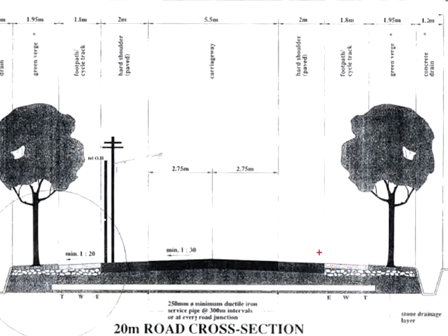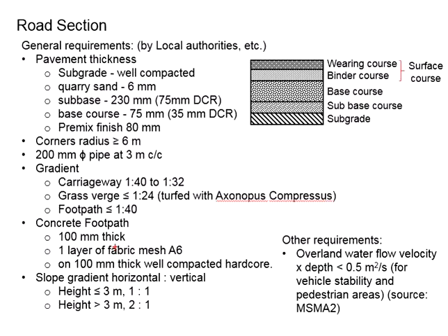Now, if the footpath is at the same level as the road surface, you may have the gradients heading towards the drain. If the footpath is slightly higher than the road surface, you will require pipes as the weep hole, directing the waters into the drain. These are the typical requirements for the footpath.